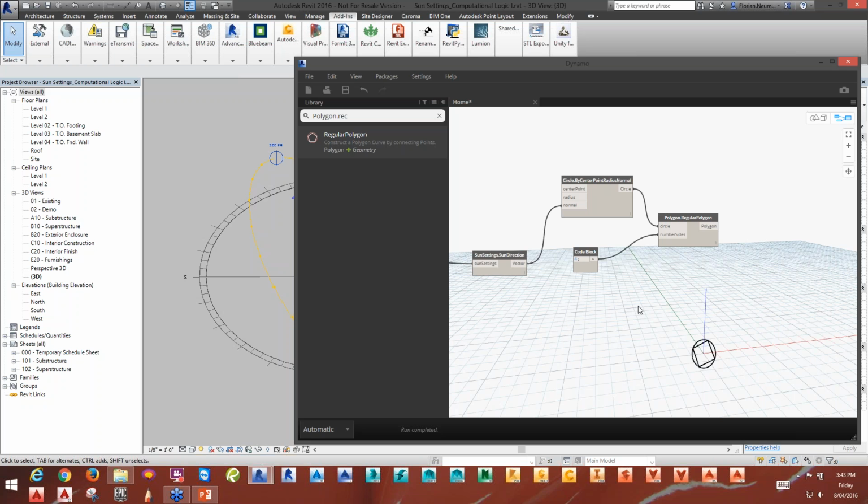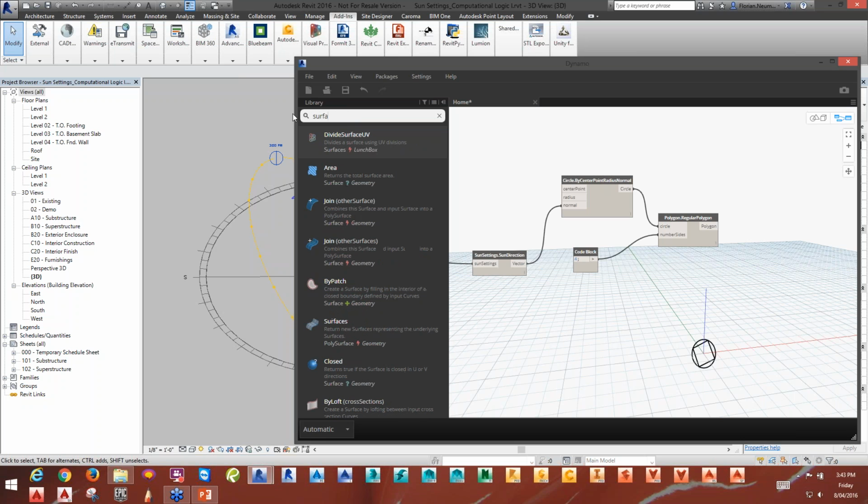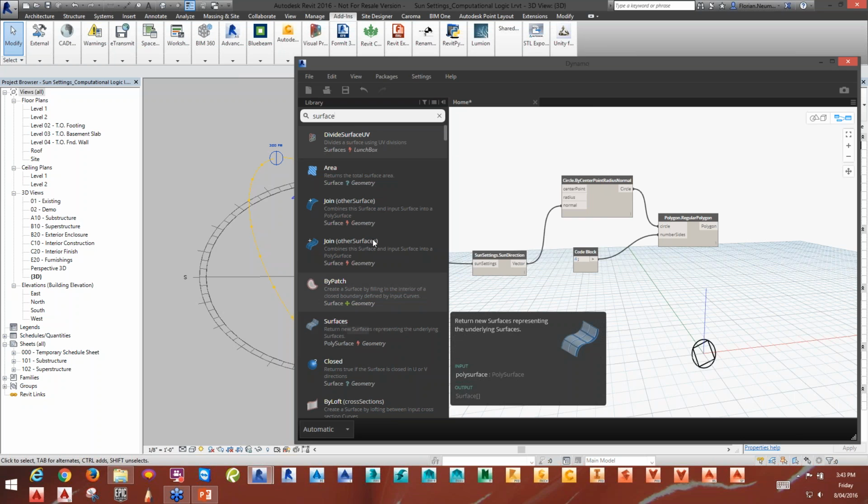It's nice that we have our four-sided polygon, which is cool, but we also want to create a surface. So we just need to look at what's the next step for a surface. It's similar to how you would do some meshing: first a bit of a sketch. We kind of produce the sketch, and then from a sketch we create a surface.